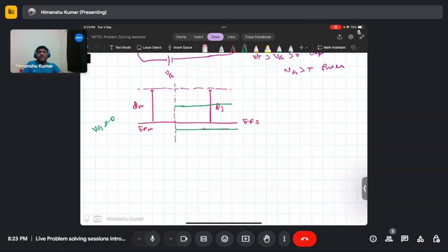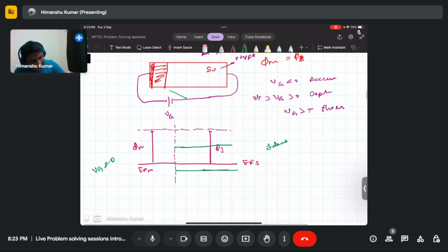Now the junction is ideal, so you assume this is a very pristine interface. So there are no interface traps. Traps happen because, if you are doing some diffusion, oxidation, doping or any growth process, or you are growing the oxide, you turn off the gas suddenly.